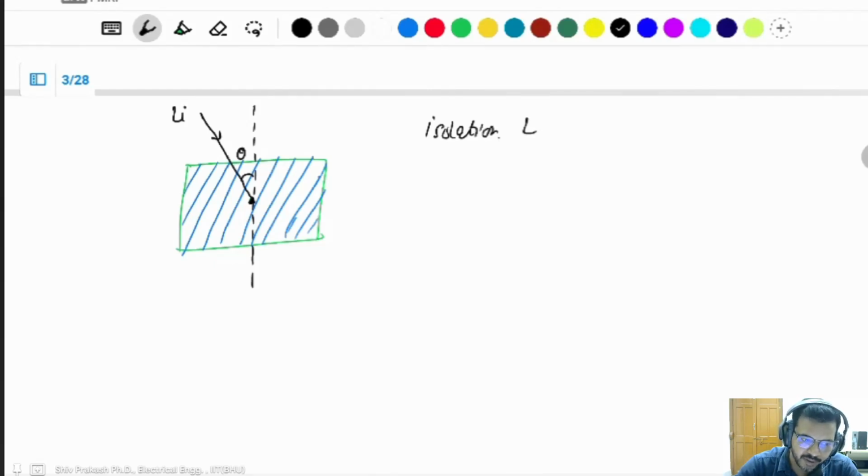It should be I, and with some angle of deflection, also cos theta. It depends on theta also. If theta is 0 degree, it means this line is exactly on this, and cos 0 is equal to 1, and it means the maximum irradiance occurs on the PV panel plate. But if there is some angle difference, then the overall insolation is reduced.